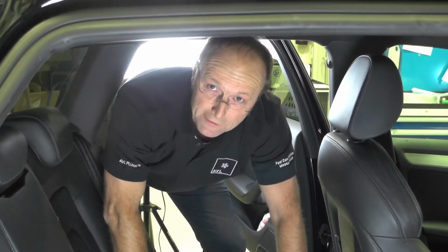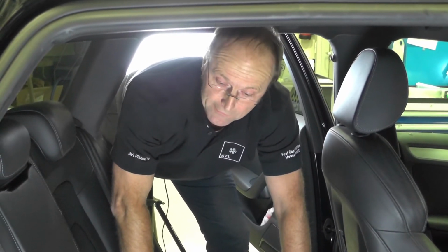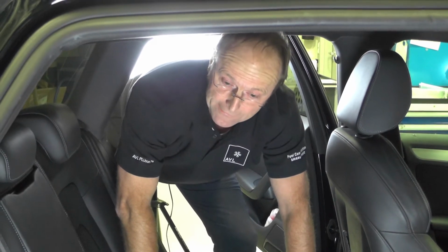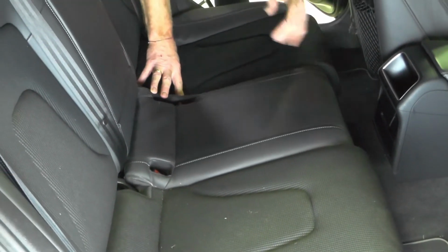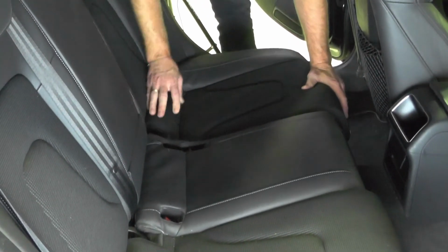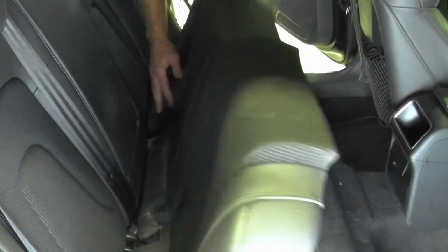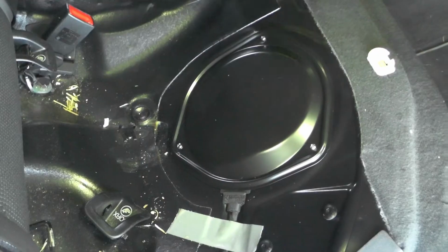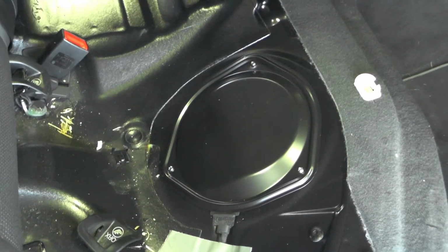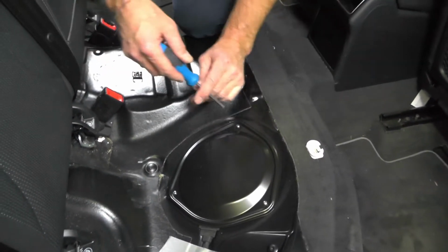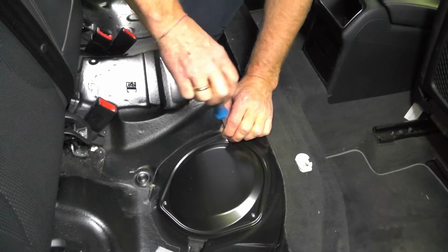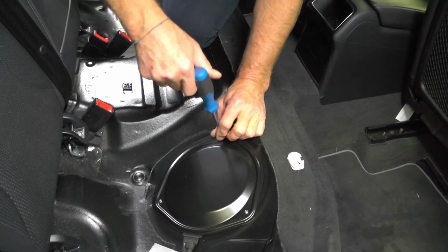The other possibility to connect to the supply line is to access the tank module. Usually there is an access under the back seat of the vehicle. So for now we are going to check and remove the back seat of the vehicle. And here we see the access lid to the tank. Okay, now we're going to remove this lid, and underneath we should expect to find the tank pump module.